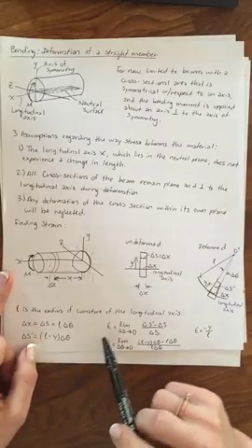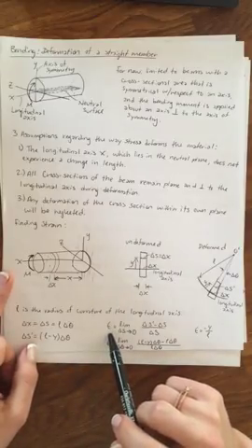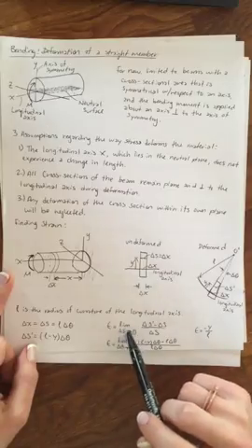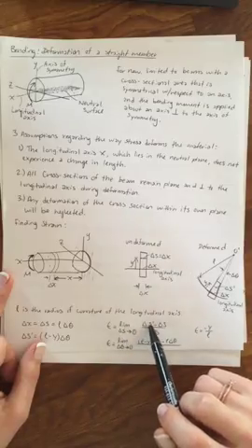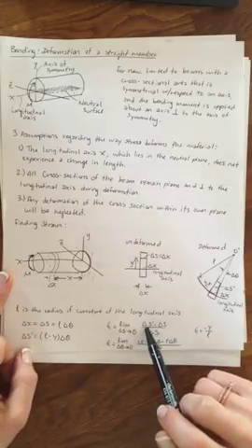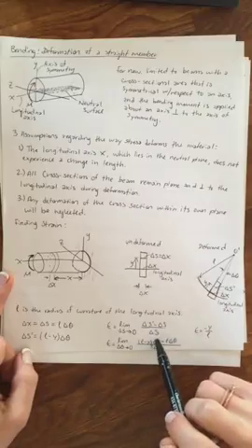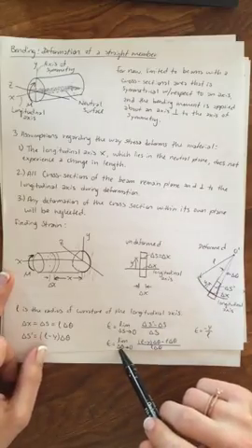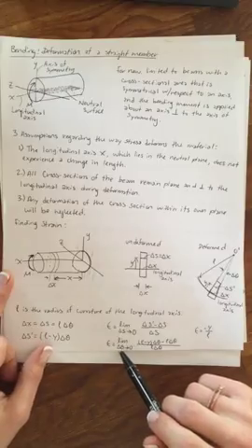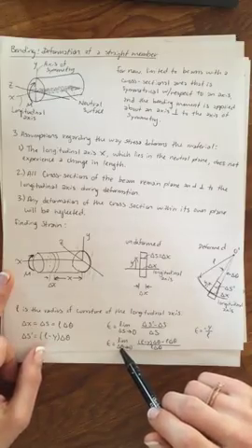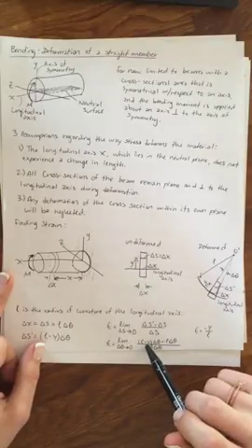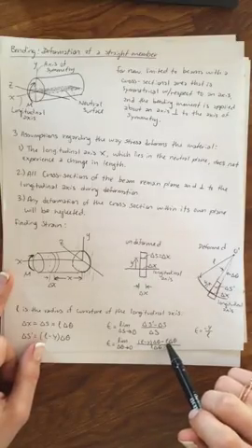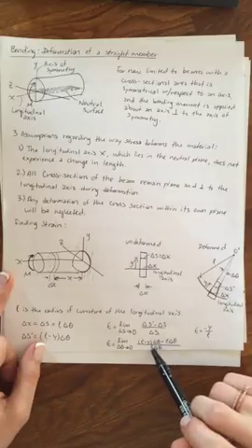So we use our definition of strain, and we can say for 2 cases, the limit as the change in the segment length goes to 0 is the new segment length minus the original over the original. And these are just based on our original definitions of strain. And then the limit as the change in the angle goes to 0 is rho minus y times delta theta minus rho times delta theta over rho delta theta.